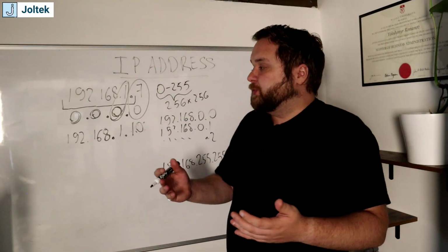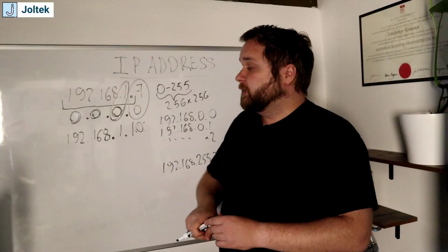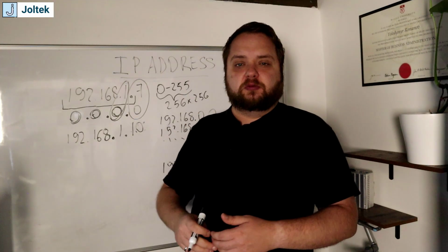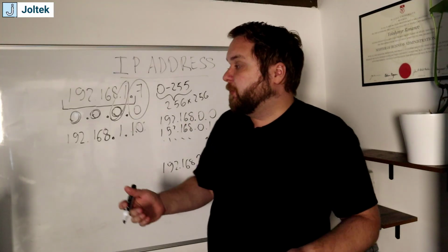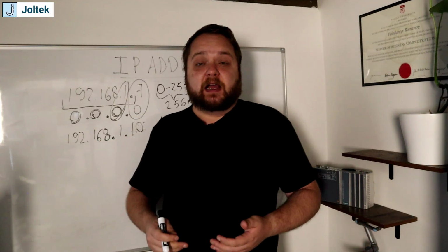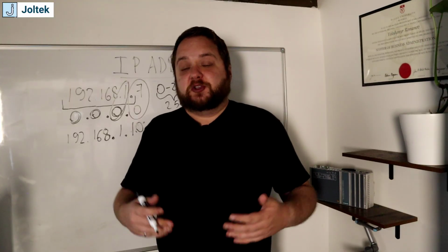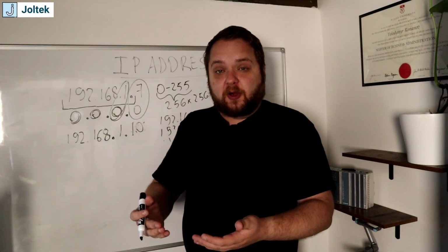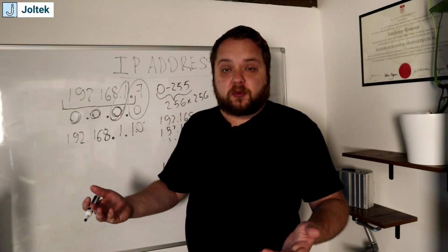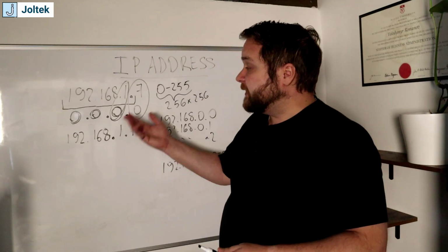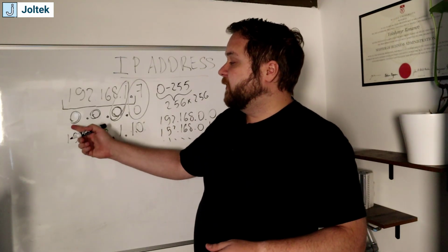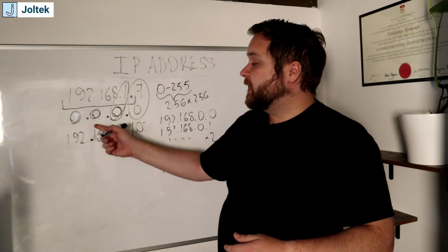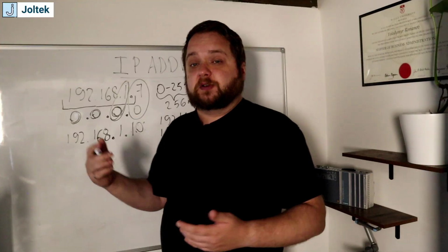So again, this is not unique to malicious intent. If I plug in, for example, my laptop just to see the internet onto a plant network, and I have an IP address that's usually set by DHCP, but if everything is open, it's just going to pick the default IP address, and I'm going to disrupt operations in that specific setting. So that's the reason why it is not very common, or I've never even actually seen this in my experience, to set the subnet mask to 0.0.0.0.